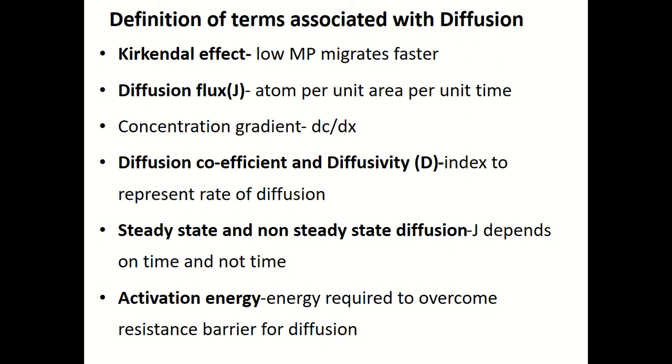Now, what is concentration gradient? We know what you mean by concentration, isn't it? If you remember the diffusion couple copper-nickel case we discussed, the concentration of the diffusing element. If you plot the concentration of the diffusing element versus the position within a solid, the resulting curve is called the concentration profile, and the slope of that curve is called the concentration gradient.